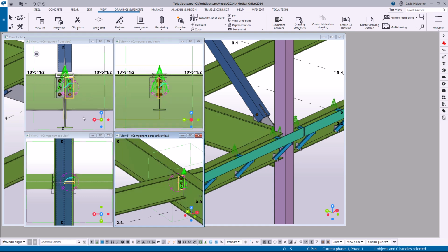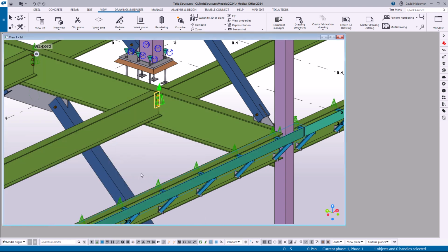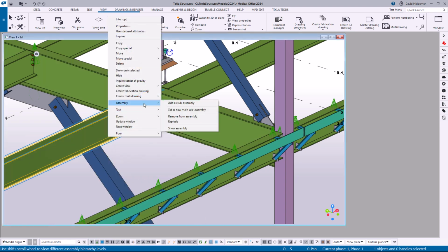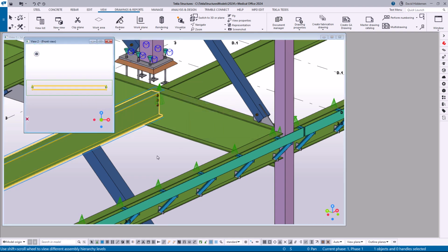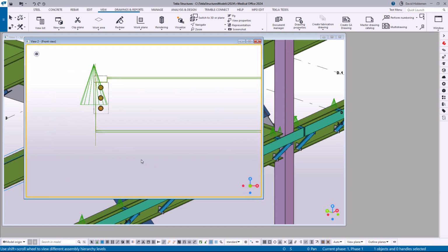It looks like the default setting in my setup, which is the US Imperial environment, for your component views is giving me transparency for both my main parts and my components. Where if I do something like an assembly default view, so let's go to create view and do just a front, my assembly front view is apparently showing things in a wireframe. That's what I'm talking about, you can customize that result, that output.